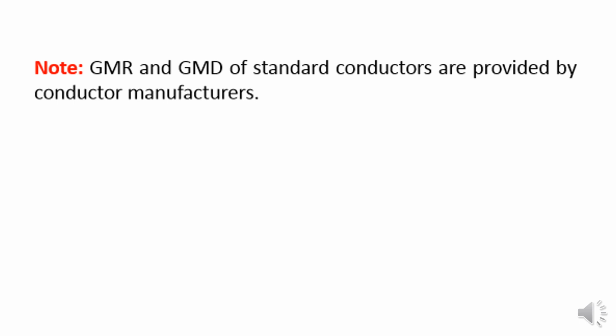There are GMR and GMD values calculated for standard conductors. The conductor manufacturer will provide the GMR and GMD of that particular conductor. So when we are given GMR and GMD, we are not going to calculate them. We will just substitute those values into the inductance equation.